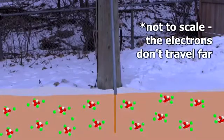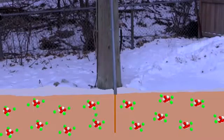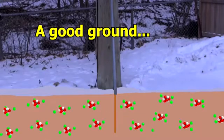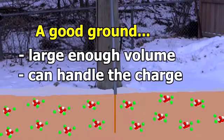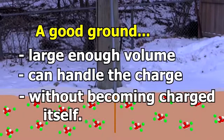To negatively charge such a large area would take a lot of extra electrons. Similarly, we could positively charge the area by taking electrons from it, leaving more positive protons than negative electrons. But it doesn't matter. The ground is such a large volume that the ground normally doesn't get very charged either way. It remains with a fairly neutral charge. So what's a good ground? A good ground is one that has a large enough volume that it can handle whatever charge you're trying to give it without it ever becoming very charged.